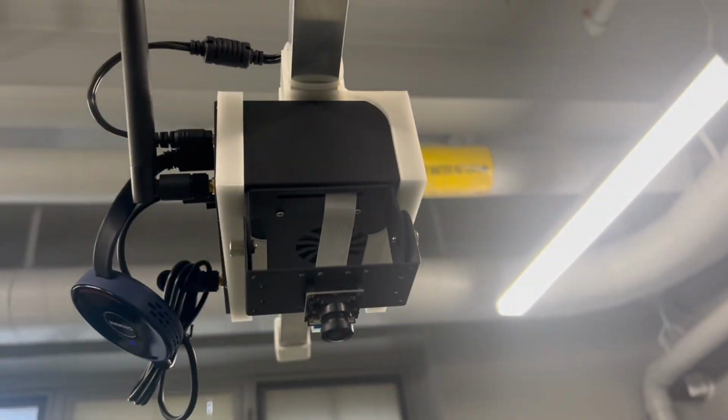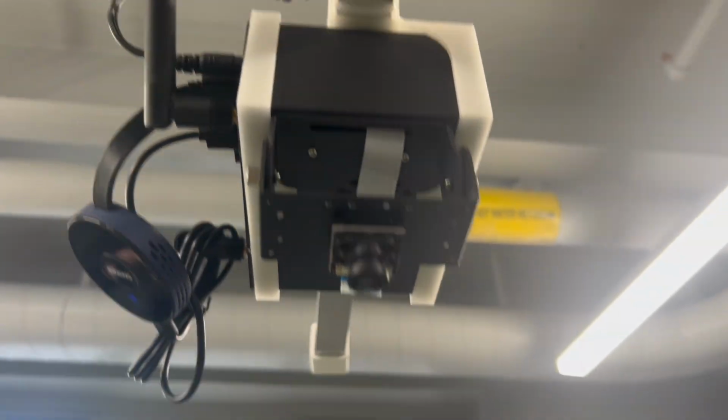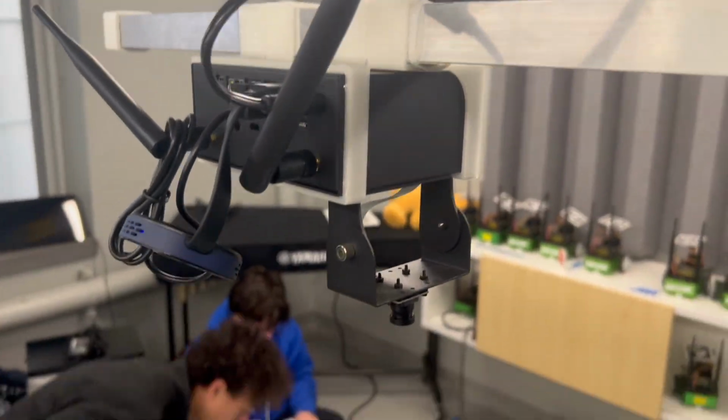In Lab 3, our team learned more about communicating with a second JetBot, the CameraBot, about how to plan a path based on a starting location and an end location, and also how to locate the JetBot using the AprilTag location. Now, to begin this lab, we first started by establishing communications with the CameraBot, where we went over to the CameraBot's terminal and found the IP address of the CameraBot, which we plugged into our code, which allowed us to establish a link between them.